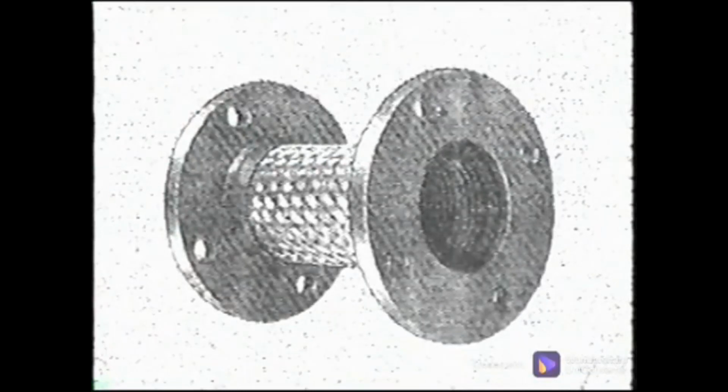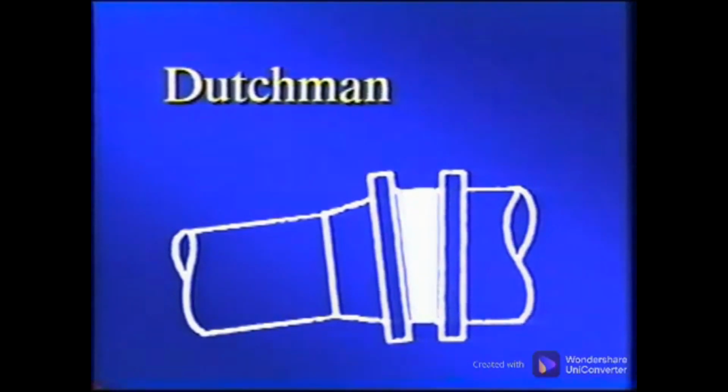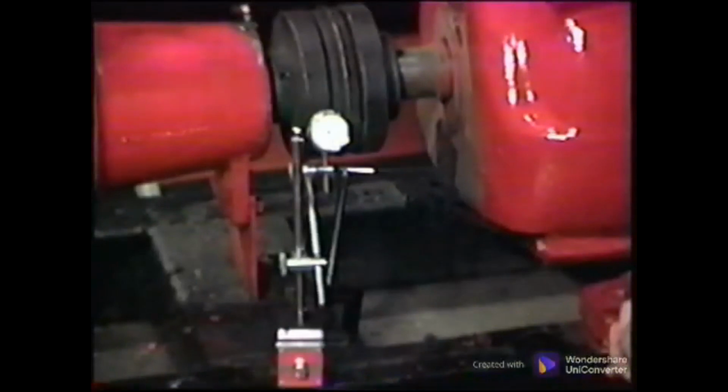Expansion joints can be used in the pipe length and are designed to absorb thermal growth and can withstand some small amounts of misalignment. However, they can only correct for so much misalignment and should not be used in extreme cases of pipe flange misalignment. In extreme cases, a customized pipe filler ring called a Dutchman may be installed. This ring should be custom made to correct for both angular and offset misalignment of the flange. There are arguments about which to perform first, the alignment or attach the piping. If piping strain corrections are made properly, it should not matter.